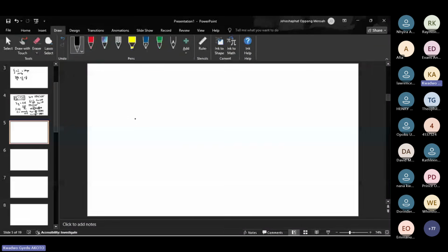So, moving on, we have the maximum number of conductors per slot. We know that Z max is equal to 760 plus 5%, right? This is 5% of the 760, okay? And then Z min is going to be equal to 760 minus 5%. Are we okay with this? Keep in mind, the question still says we should take the lowest possible number of slots. So we are still taking S to be equal to 41. All right.